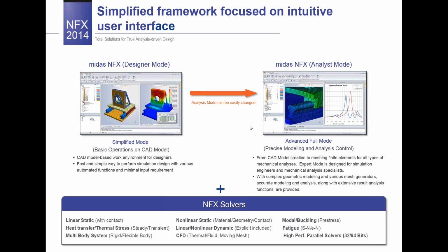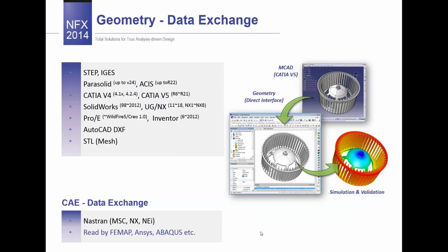The second mode is the analyst mode, which is dedicated for advanced users or, let's say, more experienced users. In this mode we have full control capability over our modeling process. So we can work directly with the mesh elements, and in this mode we have access to the full capabilities of midasNFX. Using these 2 modes, the user can perform all kinds of simulations like linear static, nonlinear static, heat transfer, linear and nonlinear dynamic, and others.